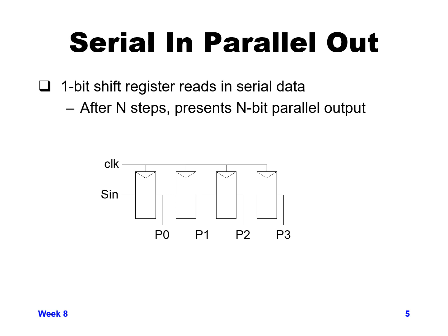And then once we get 4 cycles read in, then a different output logic will take the values of P0, P1, P2, and P3 to read all 4 of those in parallel with each other to go to some other logic. And so we're reading in a single bit serially for 4 cycles, and then once it's been read in, we take that logic and take all 4 bits at the same time and use them in parallel. So the number of steps is the number of parallel bits that we're taking at the output.